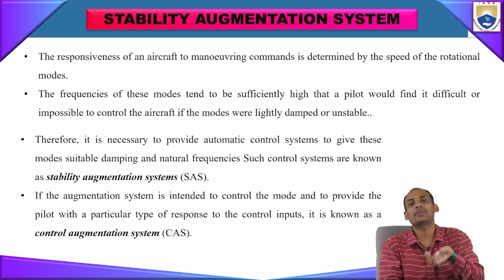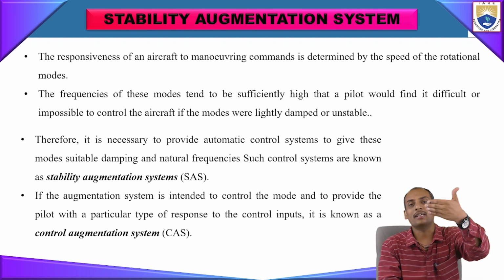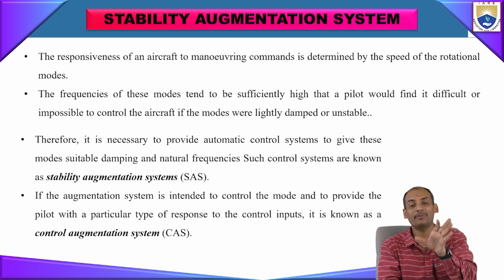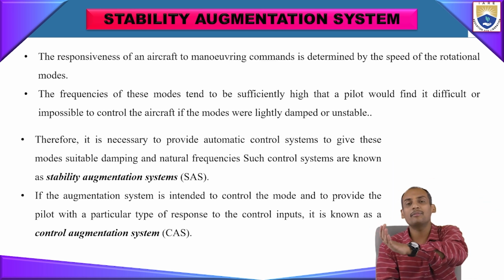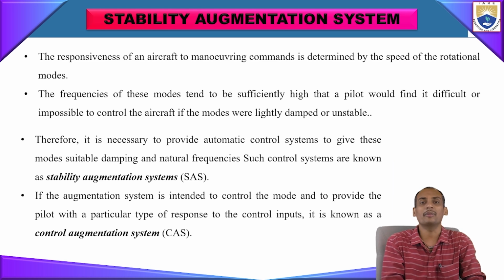If you see that frequency response diagram and that damping diagram, that is not just for graph purposes. It is showing that the aircraft can move like that. So those graphs are giving you information that a whole aircraft can have a frequency like that. I mean, frequency means the whole aircraft can vibrate like that. But here, this system can avoid that vibration and bring the system back into the stable condition. That type of system is generally called a stability augmentation system.